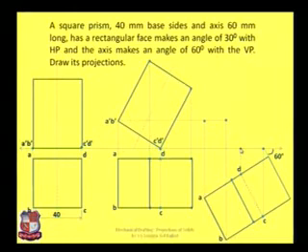Here is the fourth point. Now join all these points with a straight line like this. As point B, this corner is away from the XY line, much farther away, so this point B will be visible to us. All this point B is visible, and hence these all 4 points will be visible. So join these points with a solid line, full line.